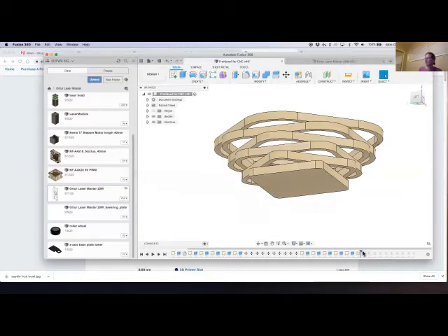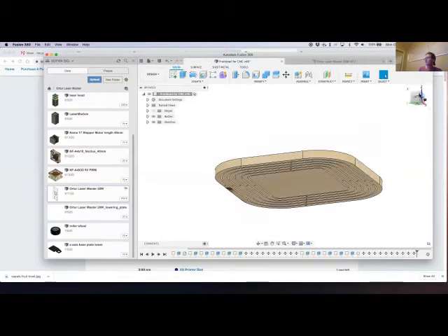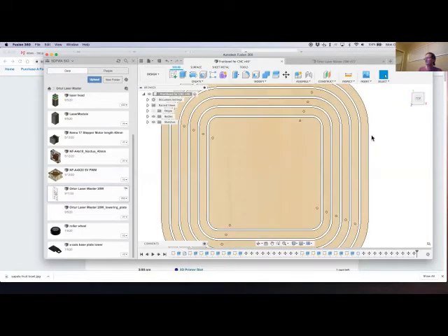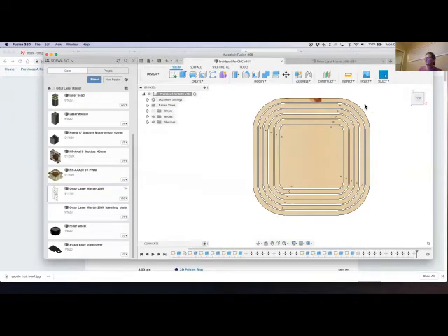So what I did was, when I have my piece of wood on the table, I put 4 additional tooling holes, 1 in each corner. I initially tried 2, but there was too much slop. That wasn't reliable. So I put 4 3/8" dowel pins, using those tooling holes between the material and the spoil board.